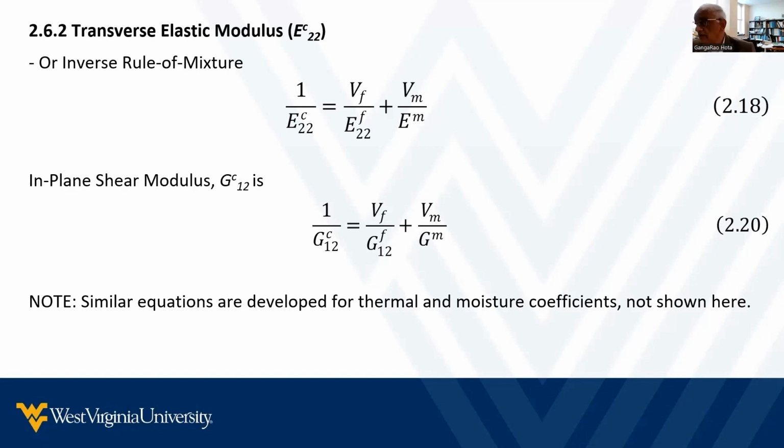So this equation 2.18 is based upon the inverse rule of mixture. And in a similar manner, we assume the in-plane shear stress on both the fibers and matrix are identical. Shear deformation is the sum of deformations of fiber and matrix to arrive at equation number 2.20.